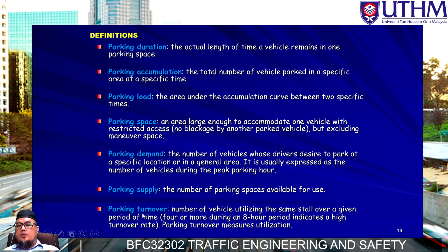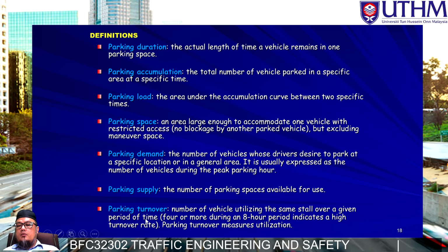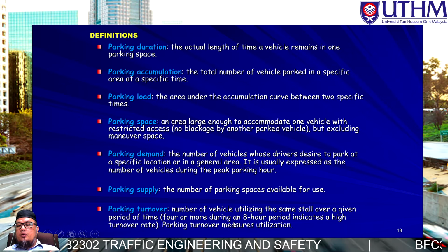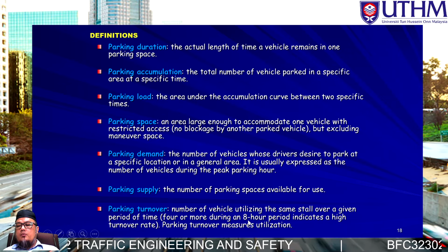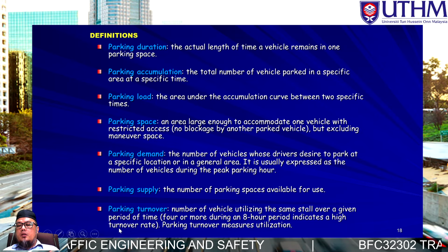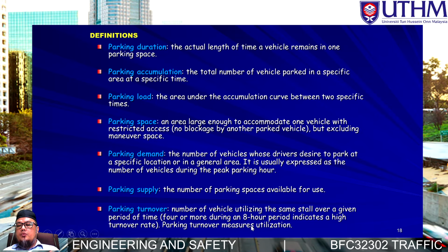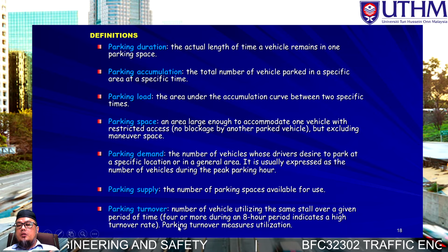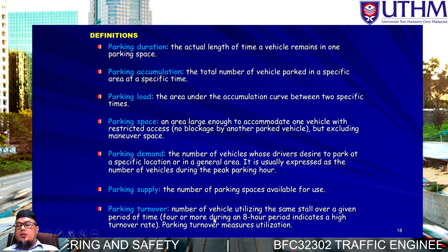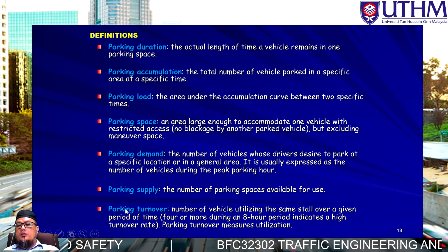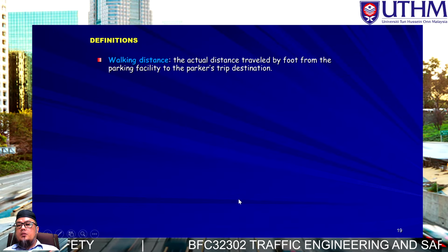Okay, parking turnover. The number of vehicles utilizing the same stall over a given period, like 4 hours or more, within an 8 hour period of turnover rate. Parking turnover is usually measured as utilization: how many percent that particular parking lot has been used. That's what they call parking turnover.